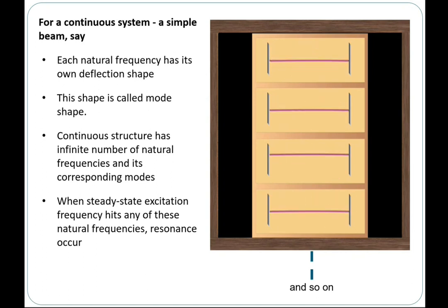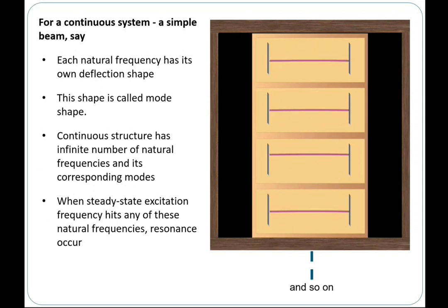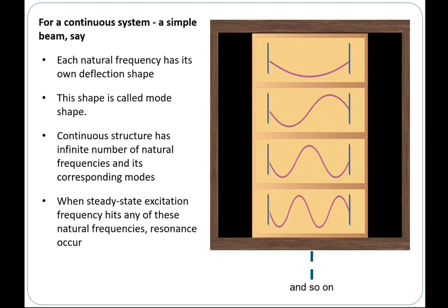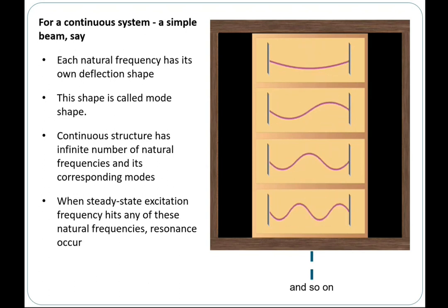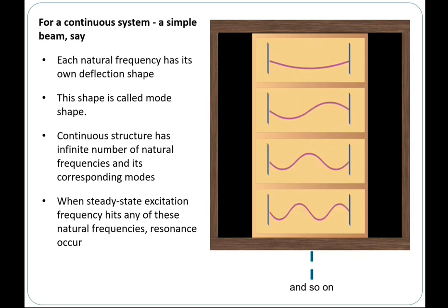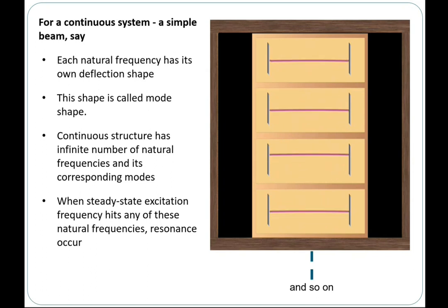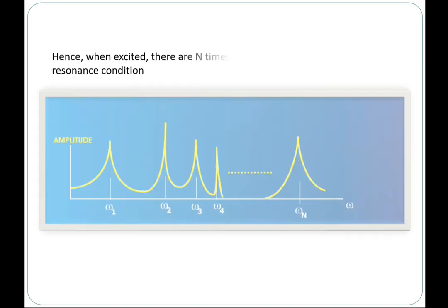High force is similar to unbalance or misalignments that you observe. So the amplification of vibration here is purely due to low resistance. In the case where you have imbalance, you have a high force, and it coincides with the natural frequency, so high force plus low resistance, then your vibration will be even higher.